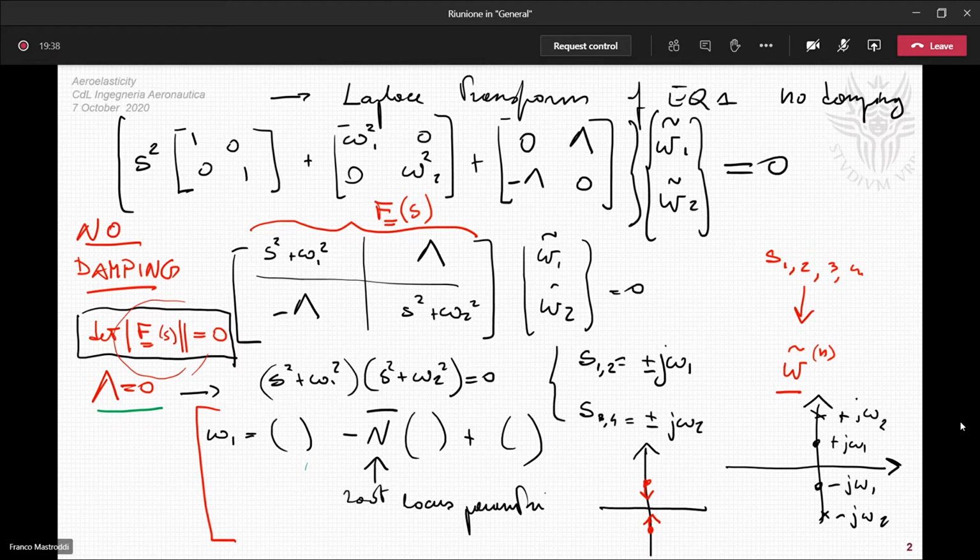So we are discovering a standard result of structural analysis, which says that in the case of conservative force, the buckling phenomenon can be reduced to a reduction of the stiffness of the system. And this is what you can see here. As a limit case, you have that a couple of poles converge to the origin of the axis, just like a very limited case. And this is the case of buckling with conservative force.